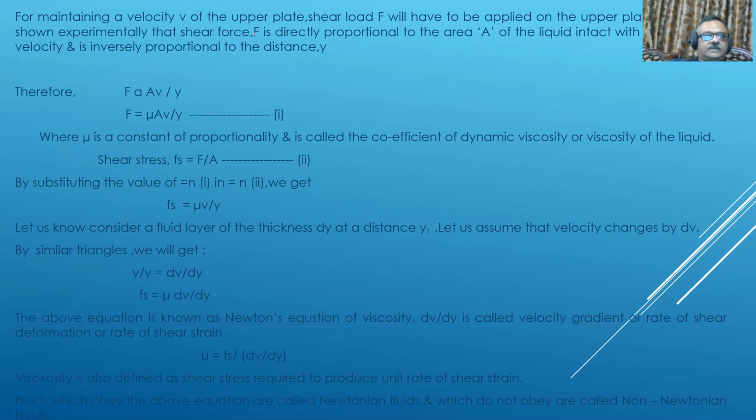It has been shown experimentally that the shear force F is directly proportional to the area of the liquid in contact with the upper plate and velocity, and is inversely proportional to the distance y.